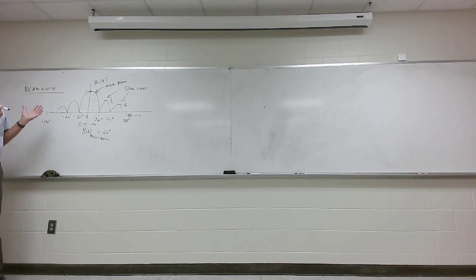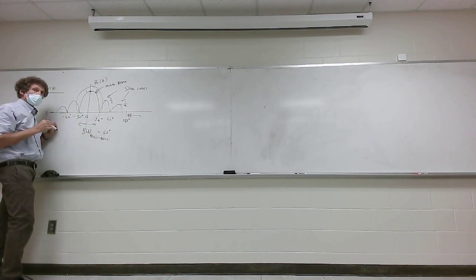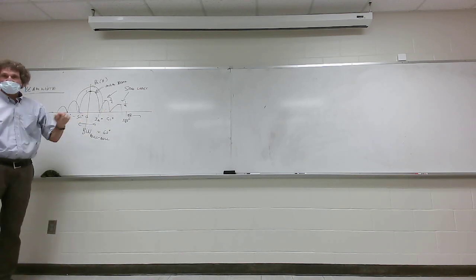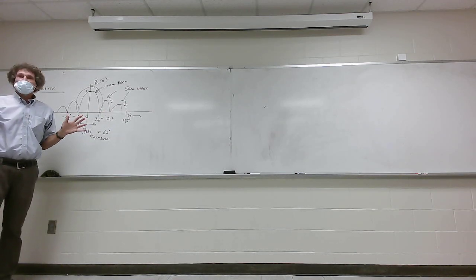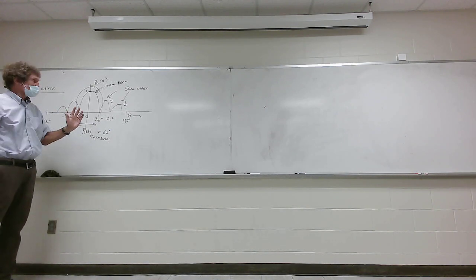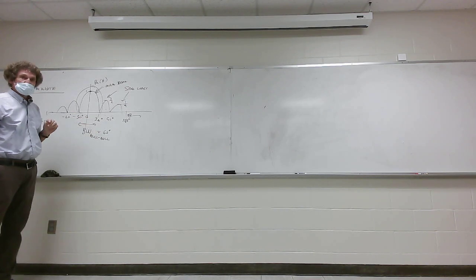Now, in general, when you look at these things, right here, 90% of the time, the only thing you care about is the width of the main beam, the half power beam width, and I'll get to that in a second, and the number of side lobes. That's it. You don't care about the power in the side lobes. You really don't care about a lot of that. You care about this right here. And usually, it's not the null-to-null beam width.